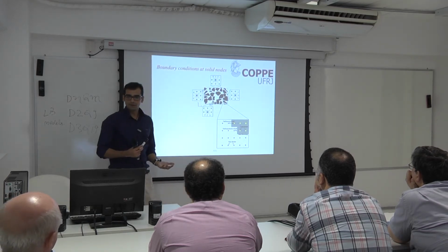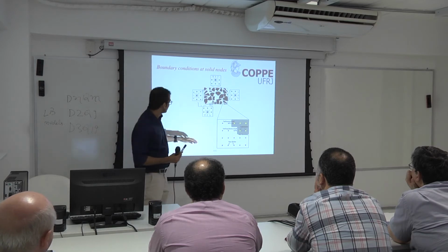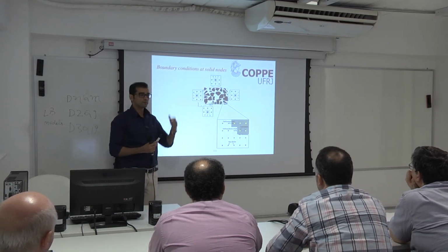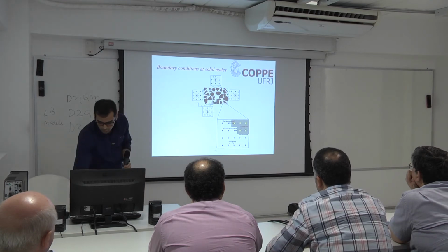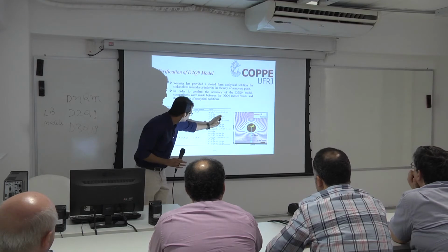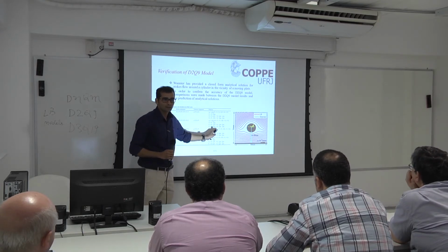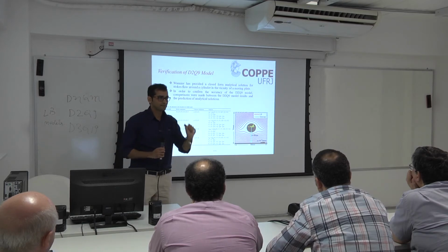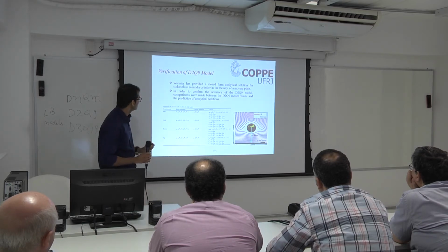So what do you do? You cannot proceed unless you calculate this distribution function. Now you go back to your propagation equation and you use these relations to calculate the distribution functions for each lattice point. Okay?